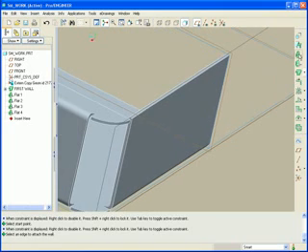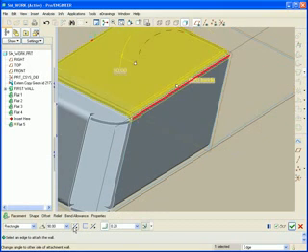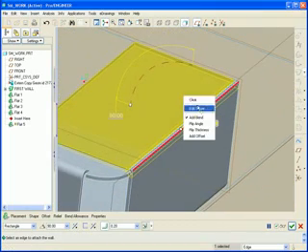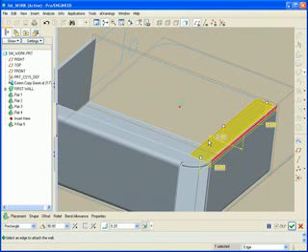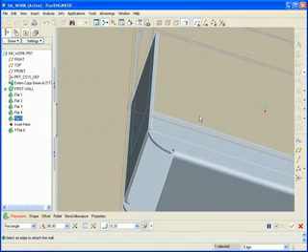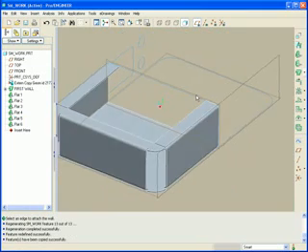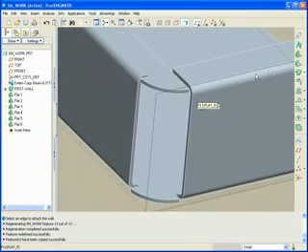Now let's just make some regular walls here. That's the way I want it. And then edit shape and bring this down. Let's make that 2-inch. Control C, Control V, and then let's pick this edge here, middle mouse. So we got two of them the same. And then how do we close this out? Watch this. We'll use something here called a flange wall.